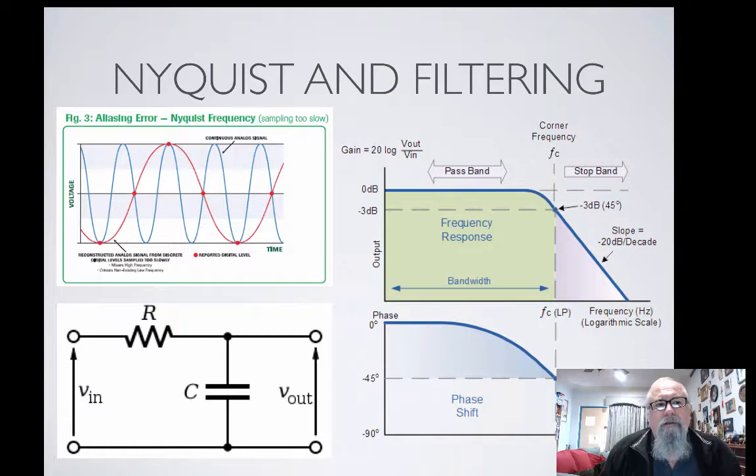The reason for this is shown in the figure in the top left. If we look at that red line, this is the samples we're receiving in, but the blue line is the signal that we need to see. Now, this is a perfect example of why this is a problem, ideal example, I should say. If we look at the first sample, we're sampling at the peak, at the lowest point of the signal that we want. Our next sample is at the zero crossing point of this signal, but the signal has actually had a great deal more information contained within it than we have actually sampled.